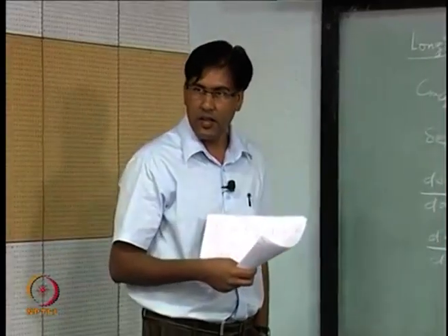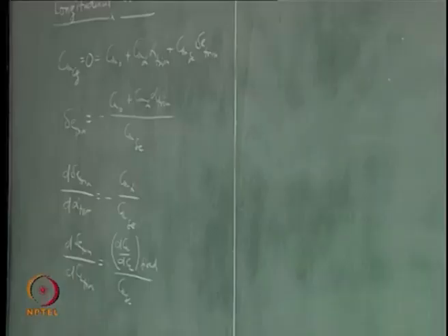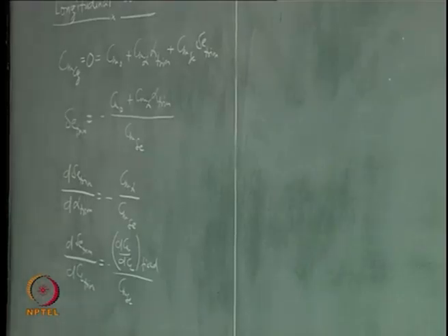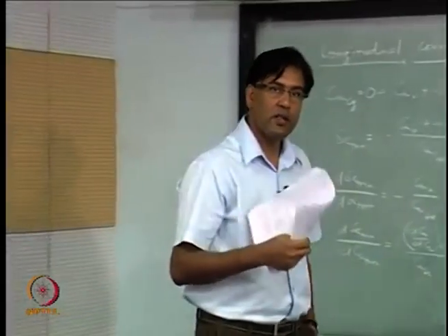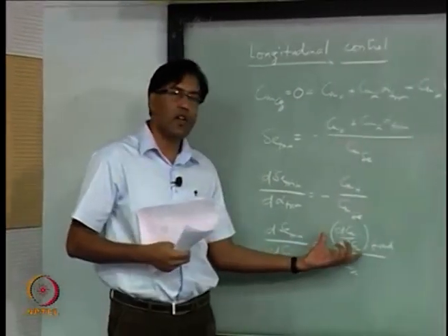And what is dCm over dCl? It is the measure of pitch stability, right, static margin, isn't it. So, clearly the amount of static margin that you have, or the pitch stability that you have, is also going to determine how much force a pilot is going to feel, right, when he is trying to change the elevator. Pilot is the one who is going to pull the stick or push it, and that force he has to apply depending on this.